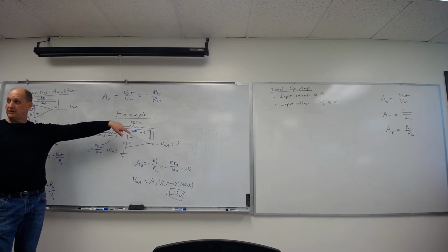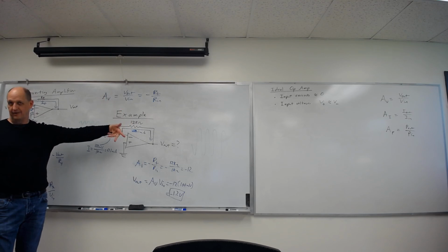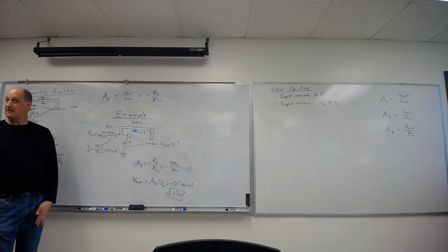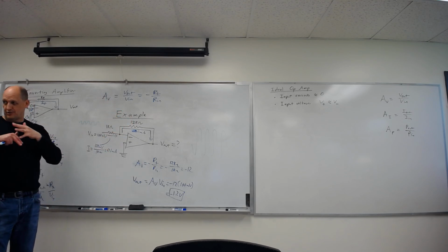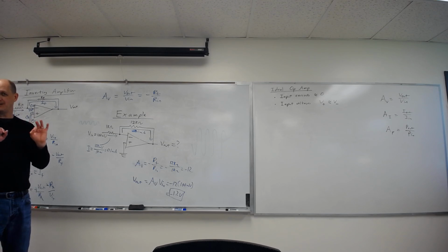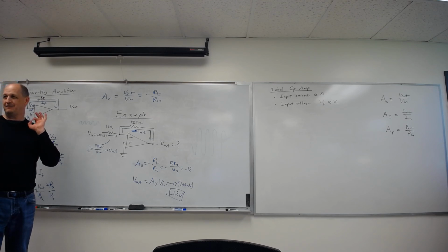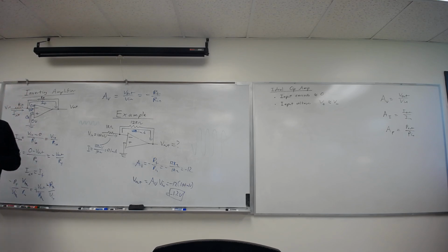The complication building them, honestly, for most people is you have to have positive power, negative power, and ground. Shouldn't be that bad, but just make sure you don't short any of them. For some reason, every semester somebody tries to short positive and ground, or negative and ground. Don't do that. This is like short positive and ground. Okay.